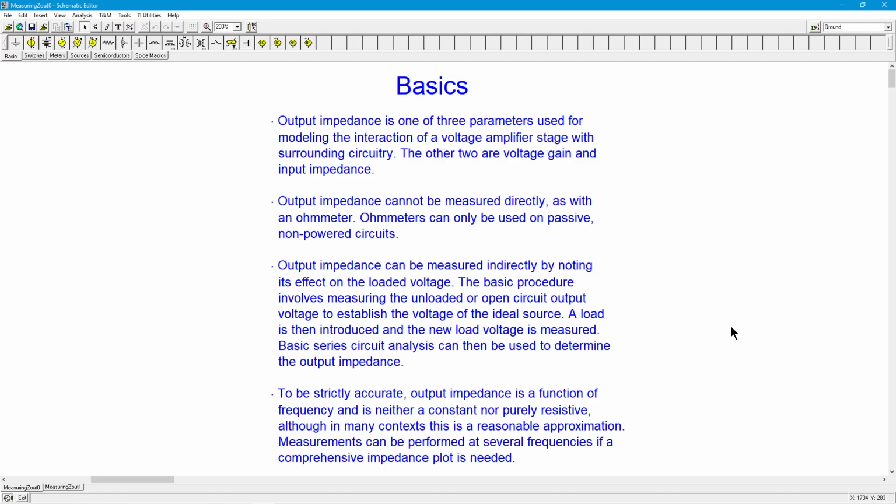So technically, it has both magnitude and phase. And we can investigate that. I'll explain in just a sec. But many times when we're talking about an amplifier, for a very wide range of frequencies, the impedance can be assumed to be relatively constant and pretty much resistive. Toward the frequency extremes, we'll start to see magnitude changes and a little bit more in the way of phase shifts. But it's not uncommon to hear something like, well, the input impedance of this or the output impedance of this stage is so many ohms. Done, right? We don't talk about a magnitude and an angle.